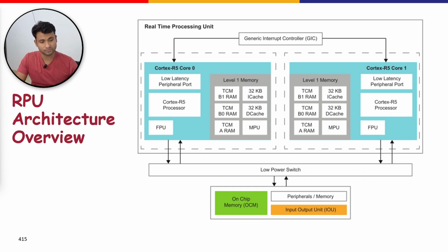So there are two primary configurations in which the Cortex-R5 processors may execute the software, maybe the FreeRTOS which is running on them. So it might be the split mode of operation, which allows each processor to work independently, permitting each core to maximize the processing performance and latency. And there can be a lockstep mode which executes the same instructions on both processors.